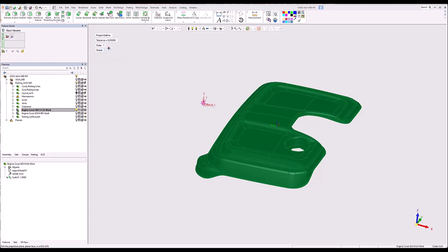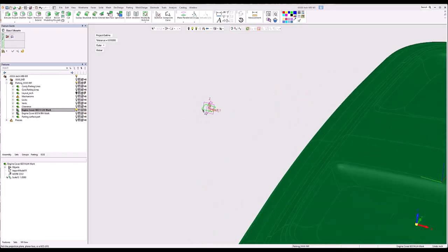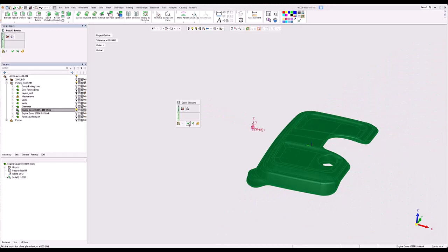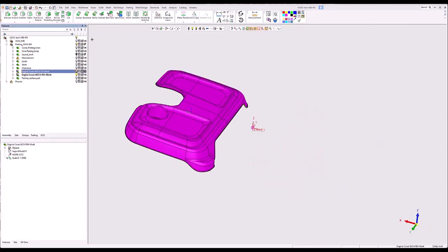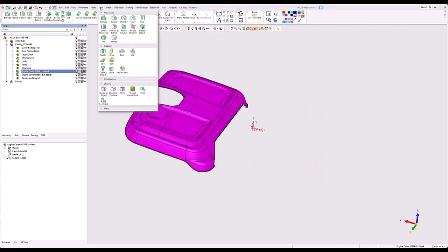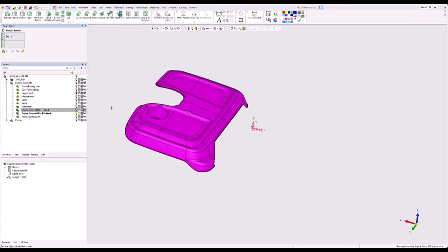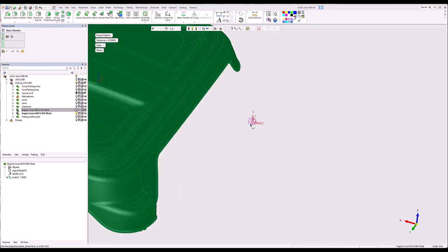I just want the outer edge, and now I'm going by project, and I'm going to pick a plane or a planar face. It'll always come up with this about looser tolerance and that. I think 10 thou's loose enough and accurate enough for what we're going to use it for. I'll do the same thing to the right hand part. Make sure I pick outer, pick a plane or a planar face.